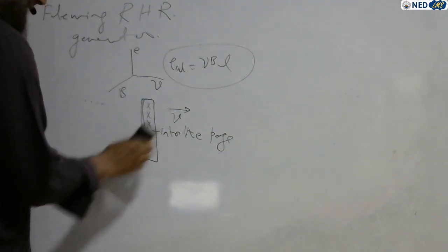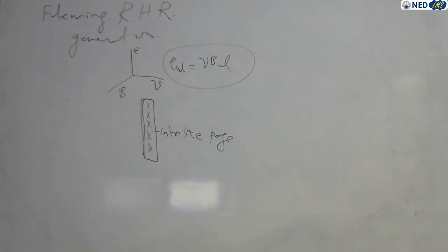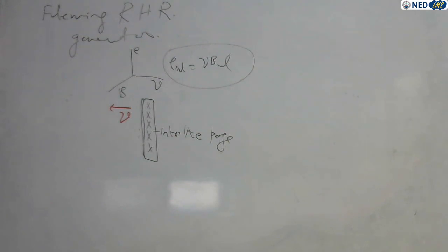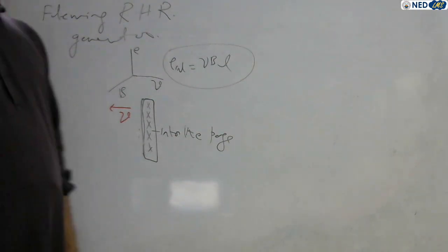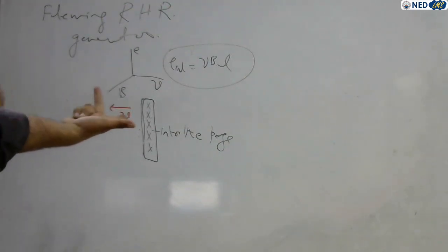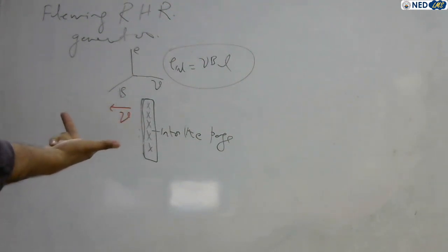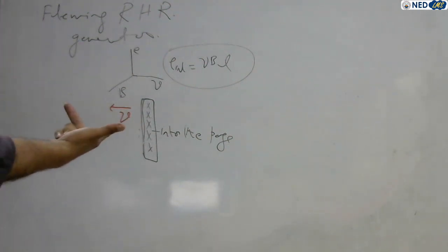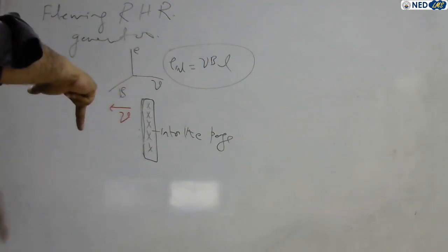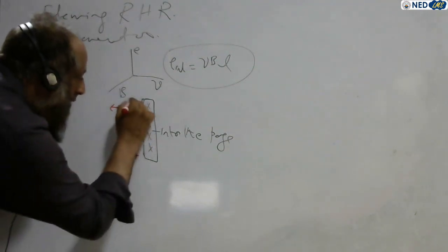Now in this case, you change the velocity of the conductor. Let's suppose the conductor moves in the opposite direction. Again, you put your right hand like this. Before, the velocity was here, but now the velocity direction is opposite. So you just alter the finger of velocity, that is the thumb. Again, your magnetic field is in, but your middle finger goes downward. So the positive of induced voltage comes over here.